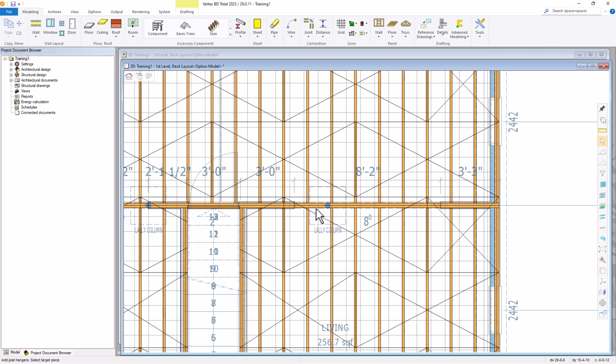This member is a 2-ply member. We can only add hangers to one side. We need to select 1 ply as the supporting member and then the joists on that particular side. So we'll select this ply. Next, we can select a crossing window and make sure that the ends of these joists are inside the window. So we'll left click and drag till we get this little box. We want to make sure that the ends of the joists are inside that box.